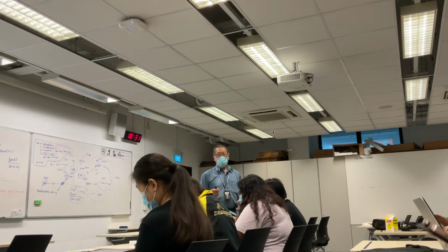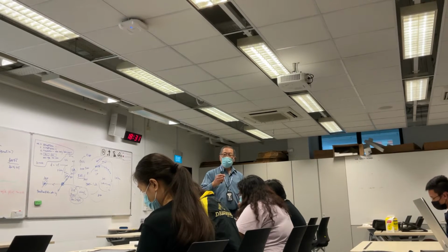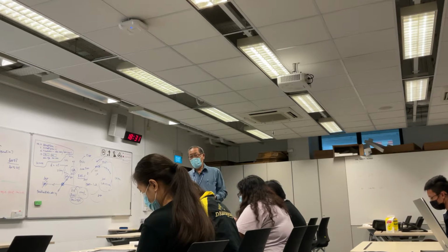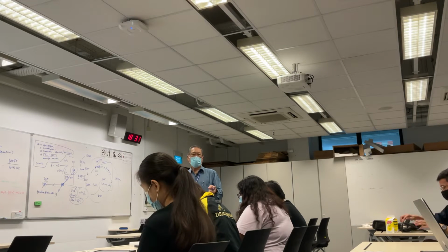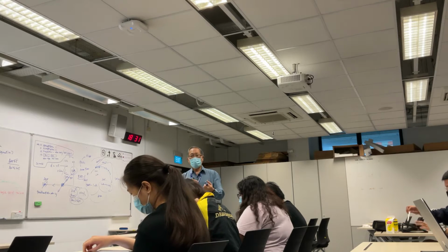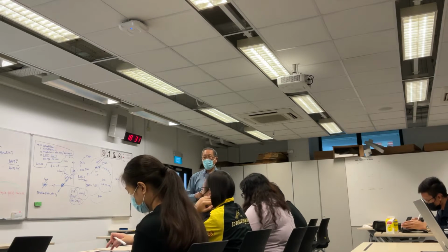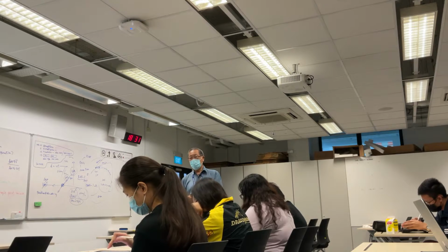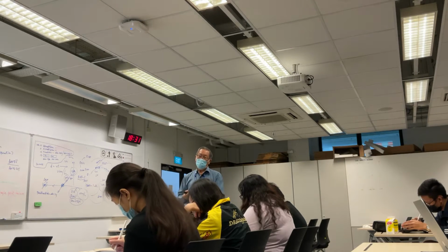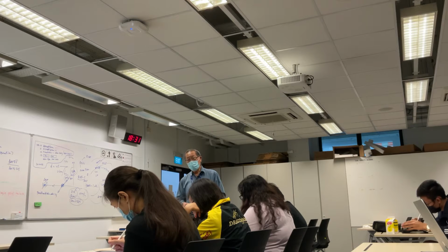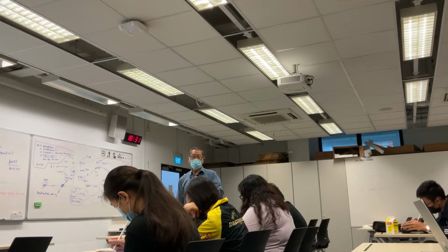Second is delayed damage, early failure. That means the reliability is shortened. Say this chip I expect to run 10,000 hours. It failed at 3,000 hours because it was zapped by ESD. Now, that is the worst case because you fix everything and then you actually interrupt the service. Okay? Right. That's not the worst.